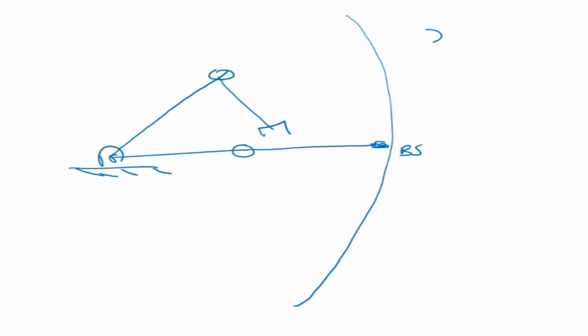Let's go back to the example I was giving at the beginning of the class today, a 2 degree of freedom manipulator. When it becomes a singular configuration here, this is singular, this is not singular. At the boundary singularity, it is losing rank. It's a 2 by 2 matrix, J is 2 by 2. The determinant of J is becoming 0 because of the singularity. Sine theta 2 is becoming 0 because theta 2 is 0 now. So we are at a boundary singularity.